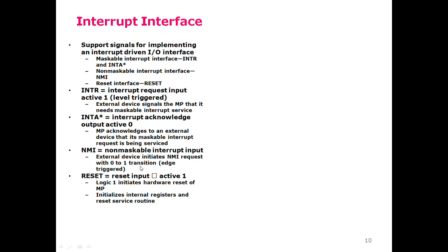NMI is the non-maskable interrupt input. External devices initiate an NMI request with a 0 to 1 transition, and that is called edge triggered, when the signal transitions from 0 to 1. The difference with NMI is that this interrupt cannot be disabled through the interrupt flag.